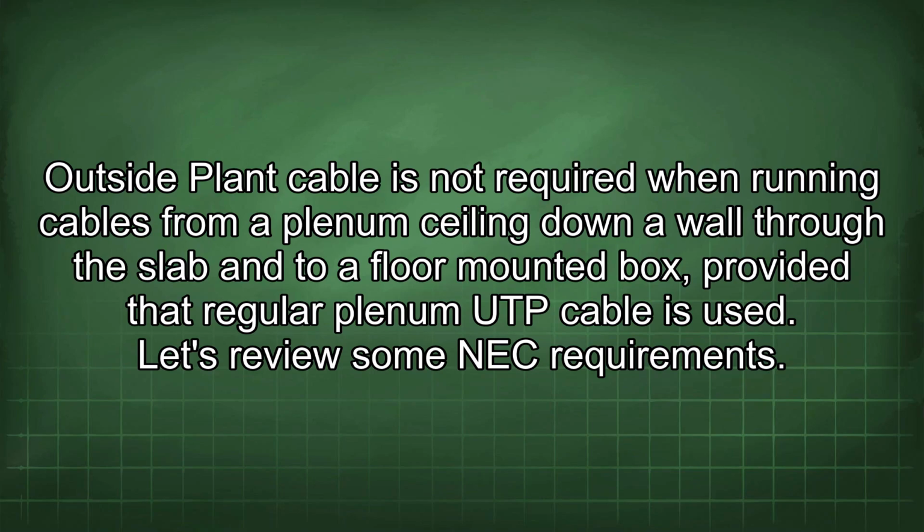Outside plant cable is not required when running cables from a plenum ceiling down a wall through the slab and to a floor-mounted box, provided that regular Plenum UTP cable is used. Let's review some NEC requirements.